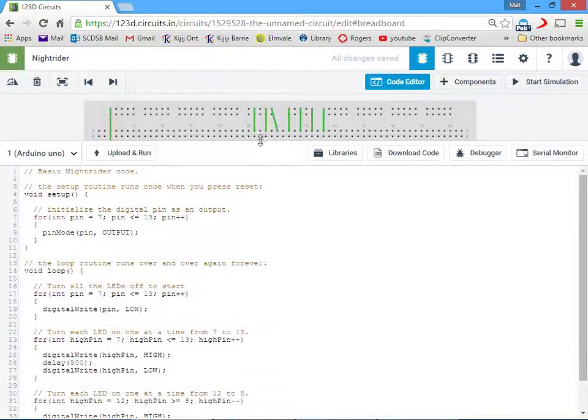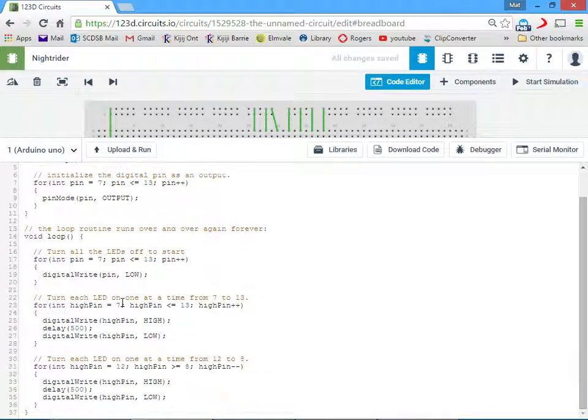So how do we do that? Well, let's take a look at the code. When we pause, we're pausing for half a second in 2 different spots. And what we really want to do is we want to change that amount that we delay, and therefore we need a variable for it. Now, where do we make the variable?